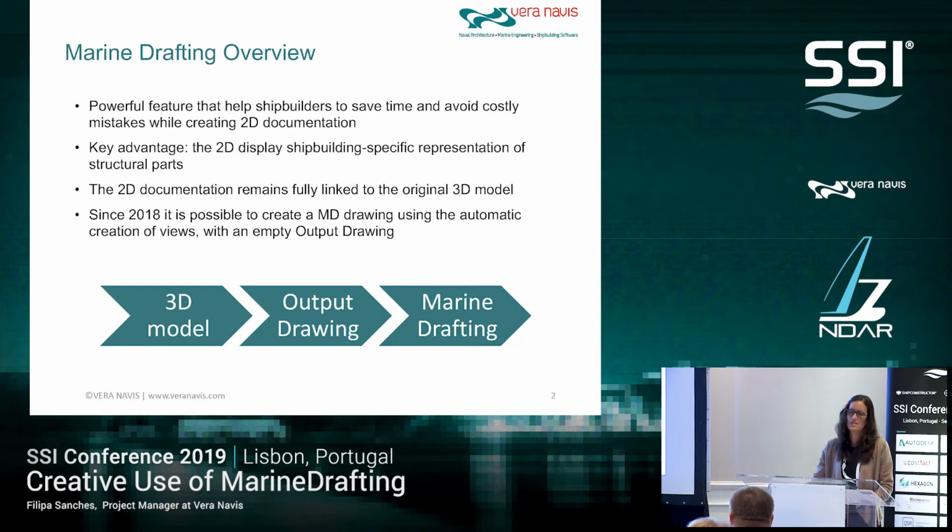Please update your license because the tool is much, much stronger now and you can do many new things with marine drafting. For example, since 2018, it's possible to create a marine drafting with an output drawing completely empty. This allows you to prepare all your production drawings. For example, if you have a team working on a structure and you know that there will be changes and even that there are parts missing, you can prepare your drawing and then it will be much faster to produce all the drawings that you need.